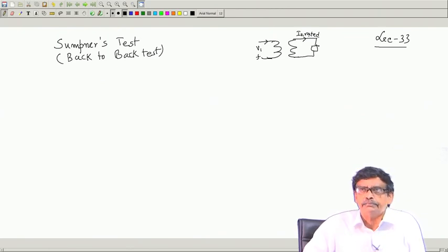What is the difference if the temperature rise is different? Because in the open circuit test there is only a very low temperature rise. Because of the temperature difference, the resistances of the windings, which represent losses, will change their values.